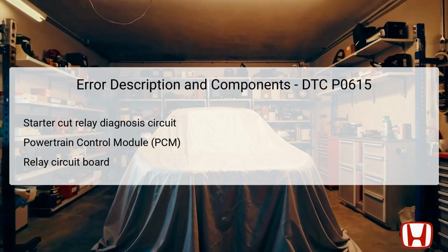When dealing with DTC P0615, it is important to understand the components involved, particularly the starter cut relay diagnosis circuit and the powertrain control module, often referred to as the PCM. The starter cut relay controls the power to the starter motor and is integral in ensuring the engine starts under specific conditions. The PCM, which is the vehicle's computer, manages this operation by monitoring input voltages.